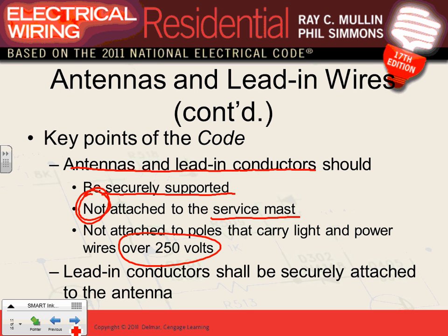Lead-in connection shall be securely attached to the antenna. They talk a lot about, guys, when you read through these articles, they do two things. Number one, all these cables have to be secured. Number two, you separate them from power. Number three, you ground the shield. And number four is it has to be done in a neat and workmanlike manner. So don't do a sloppy job.